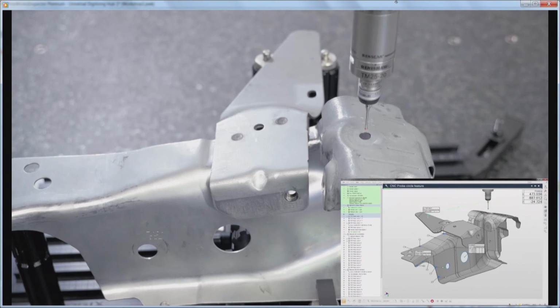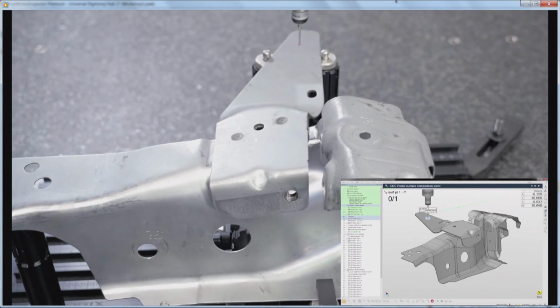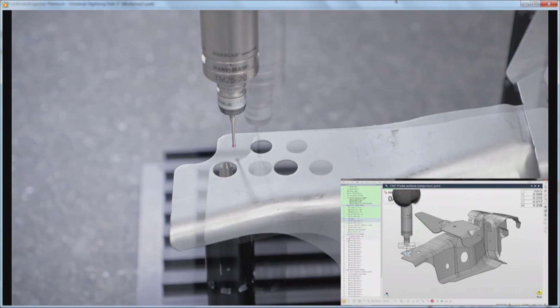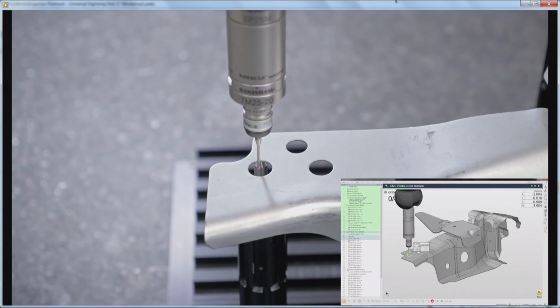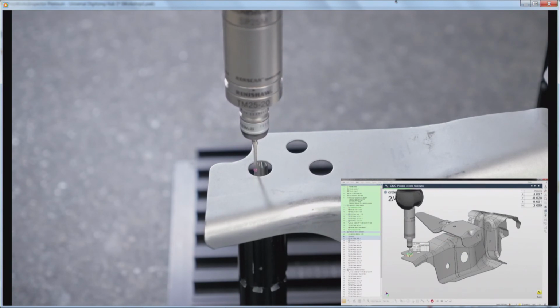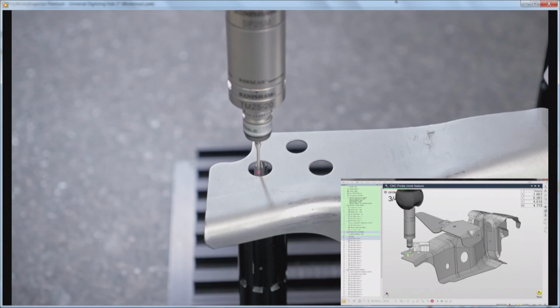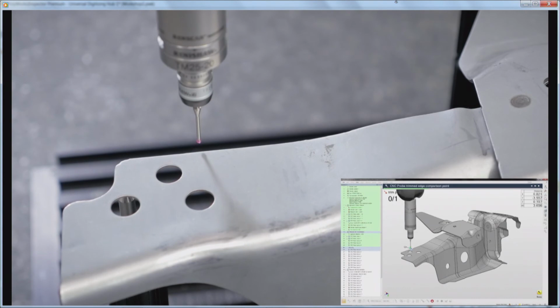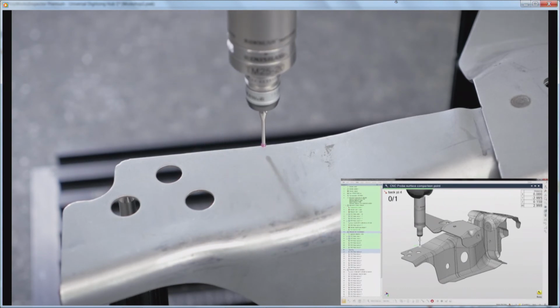Once this is completed, we will measure our surface points. And just because I'm sure you all get the point, I'm going to skip all the other alignment objects. And once the alignment is computed, then we measure everything we can measure from the top orientation. So that includes the two circles that are here, in addition to all the trimmed edge comparison points that we have to measure from the top orientation.